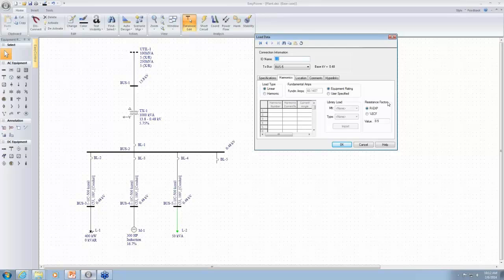And earlier in one of the charts, we showed that the resistance for a conductor with the skin effect increases in proportion to the square root of the frequency. So that square root can be expressed as an exponent here. So that means 0.5 exponent.